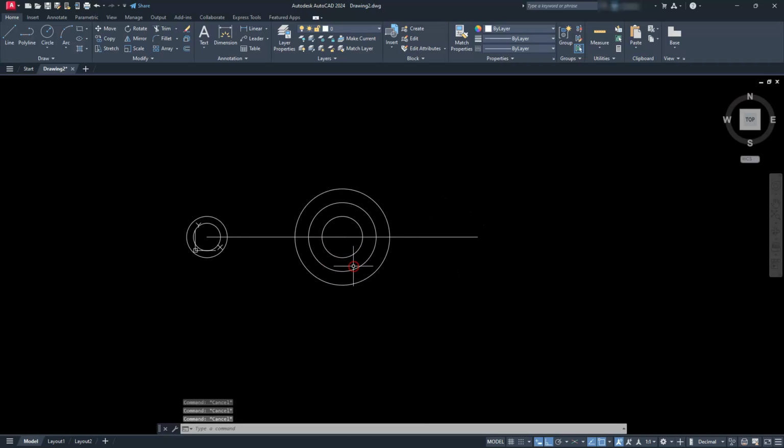All right, let's go ahead and place our other circles here. We have this big circle we can copy. Once you select it first, and I'm just pre-selecting the circle, use the copy command, go from this center or midpoint to that endpoint, because this one has a radius of 35. And it's going to be the exact same one as my other circle.